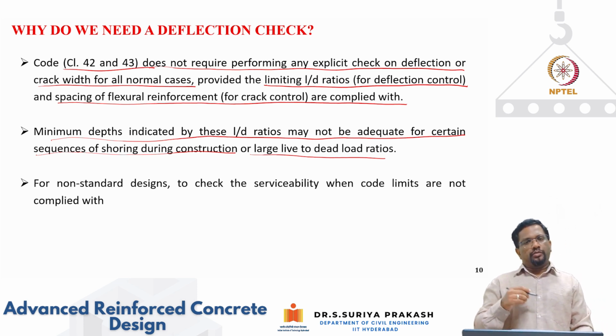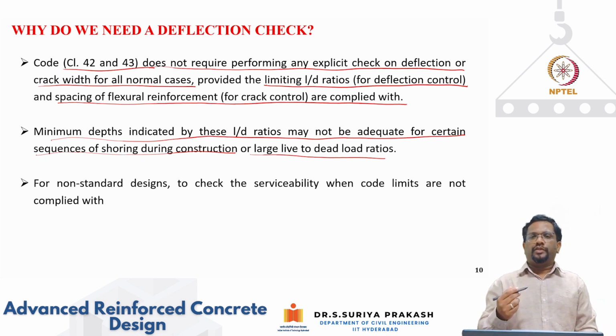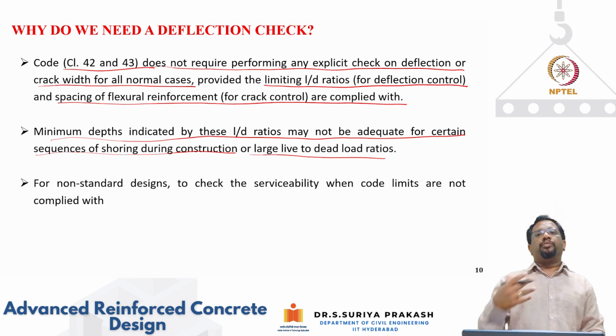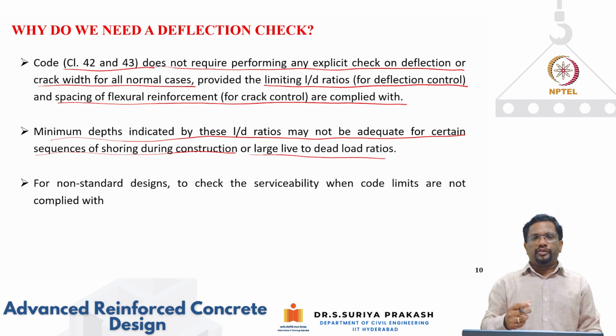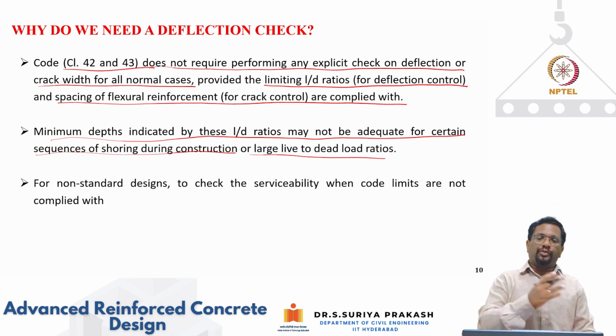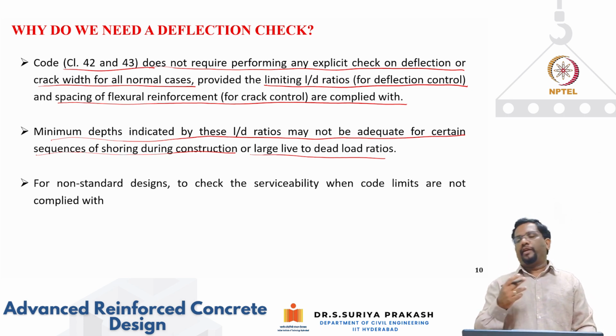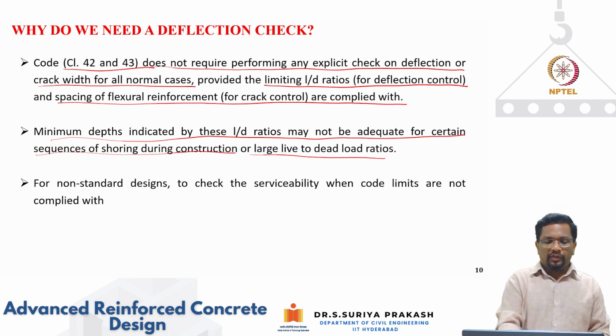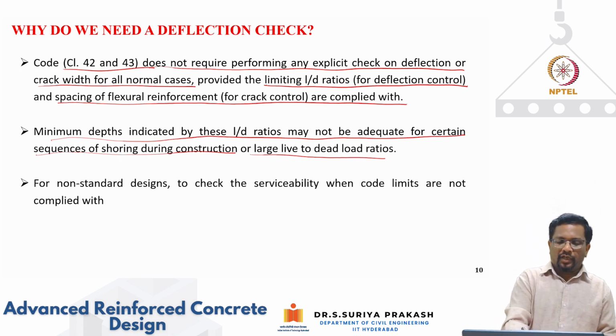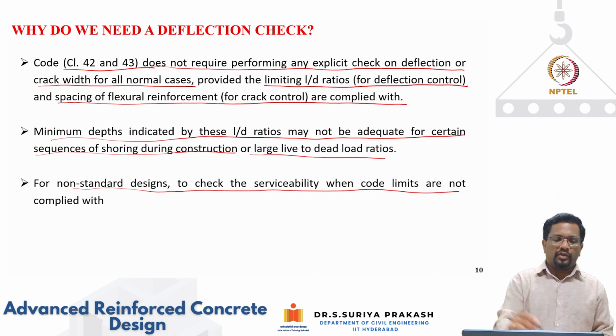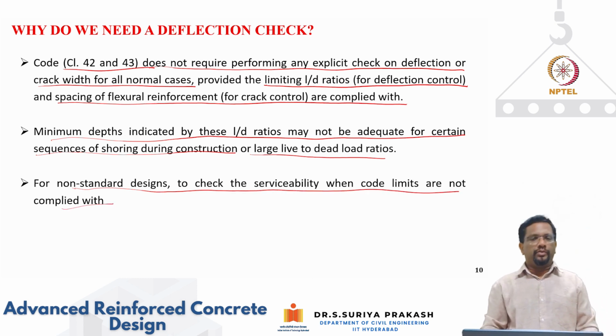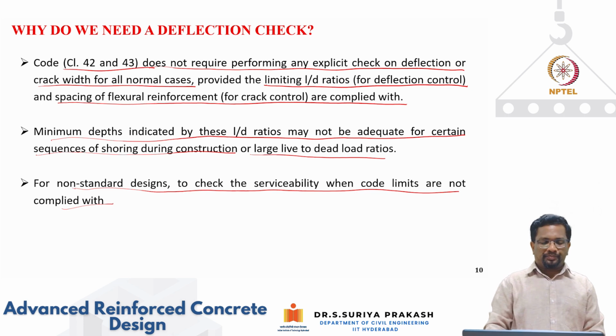Sometimes design engineers exceed the provisions given in the code, or sometimes we also violate the provisions. In those cases, to make sure that we are not violating the performance requirements, we need to do serviceability checks. For non-standard design, to check serviceability when the code limits are not complied with, we need to go ahead and do the deflection checks explicitly, and make sure that the deflections are within the allowable limit.